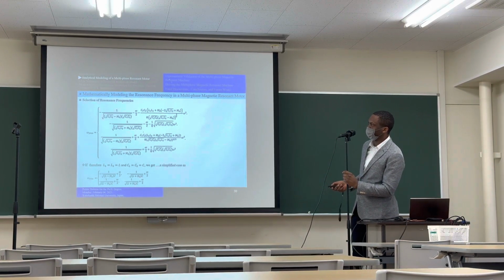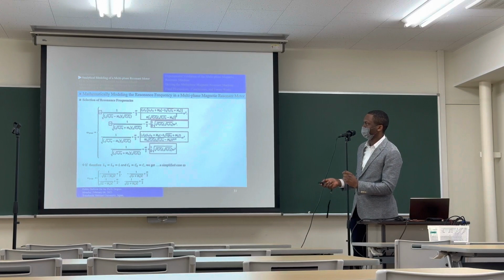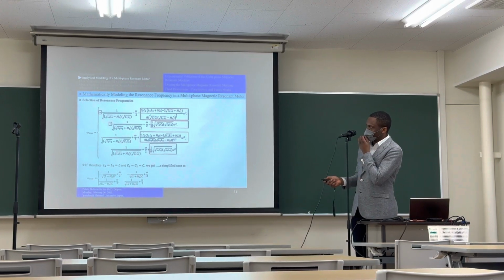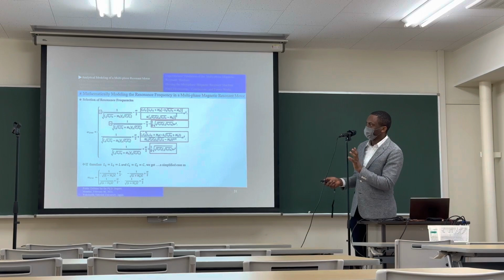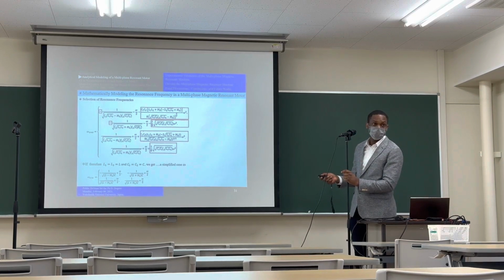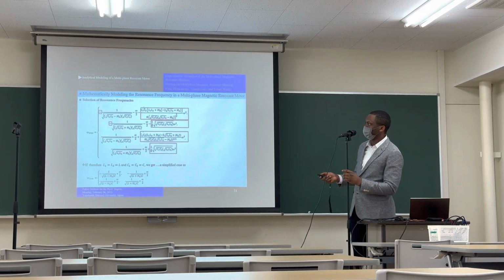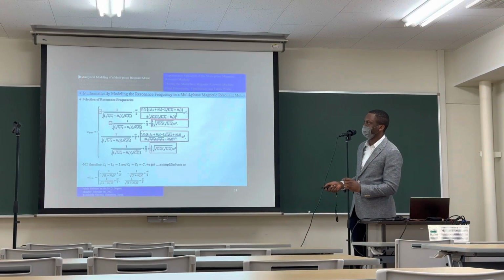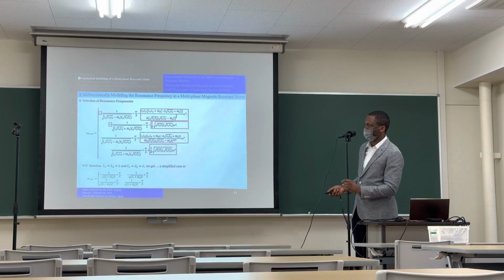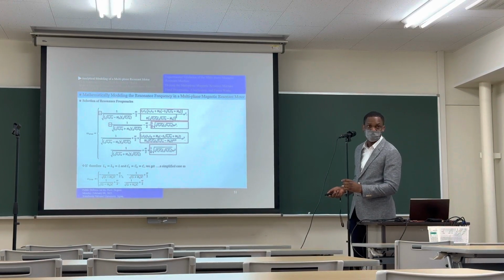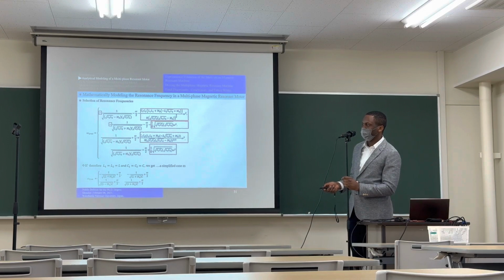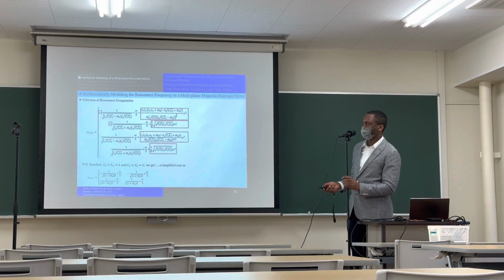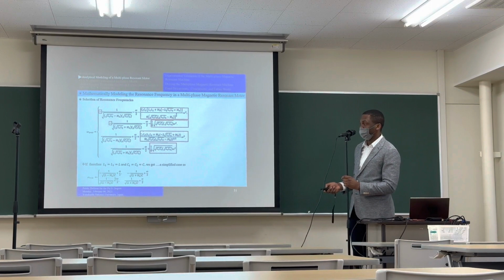With this model of the resonance frequency, we realize that from the domain of definition, we can eliminate all frequencies that are in the negative domain, and we can eliminate all the higher frequencies that are smaller because their effects are very small. So we just have the most significant part of the frequency, and the frequency model is in this way. We have frequency splitting at resonance. With this formula, if we calculate the inductances and we know the frequency, we can estimate the capacitor that we need to add to the coils.